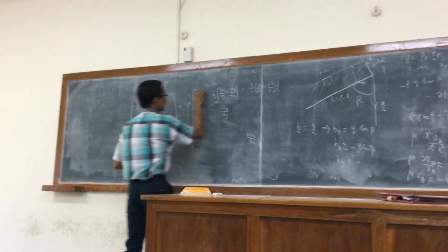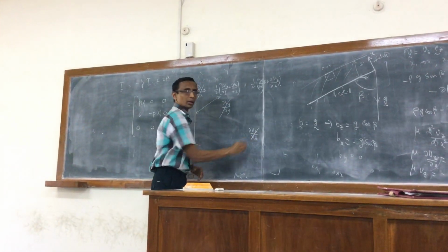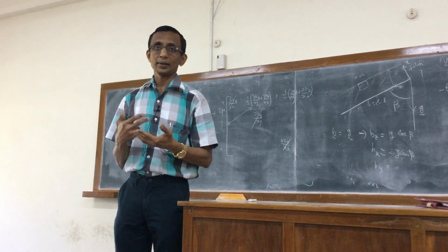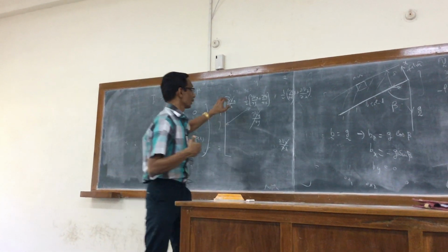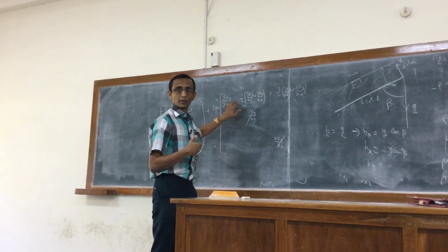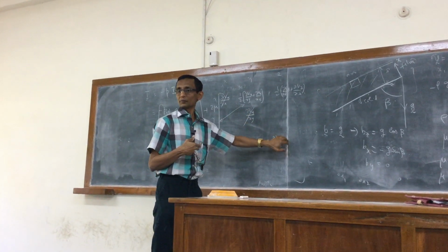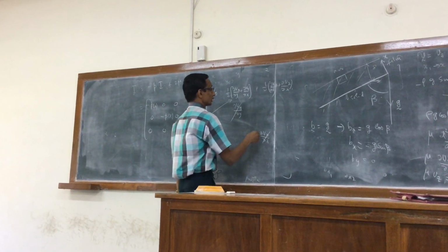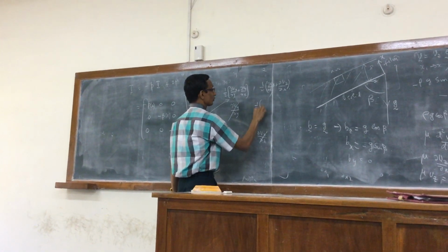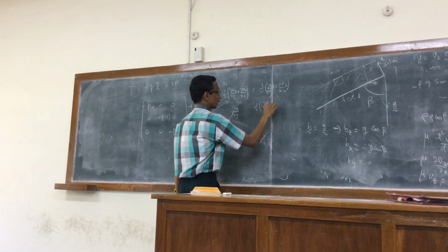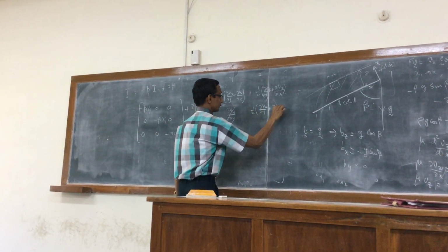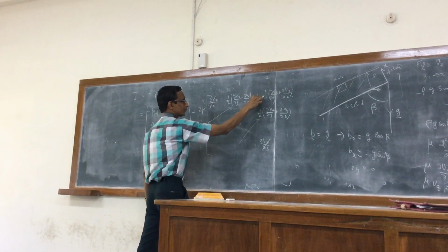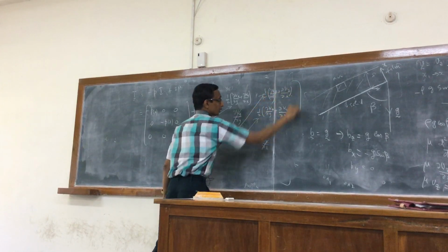So we see that there is no contribution at all in this particular case for the normal stresses from the deformation tensor, because all the diagonal elements are 0. vx is 0, so this is 0. vy is 0. The continuity equation says that dvz by dz is 0. Everything is 0 along the diagonal, and this would be half dvz by dx plus dvx by dz, and that is what you would also get here.